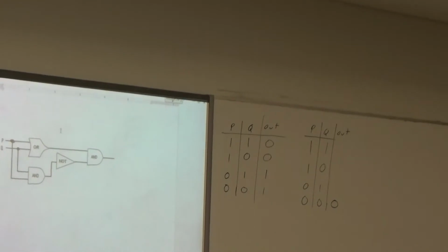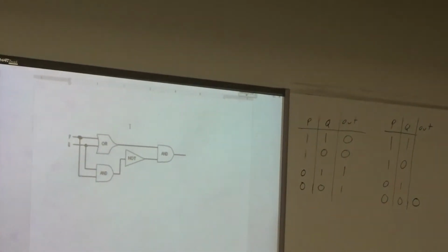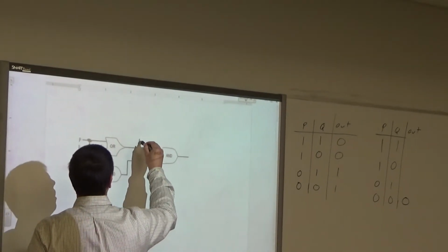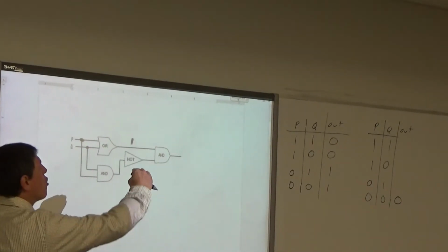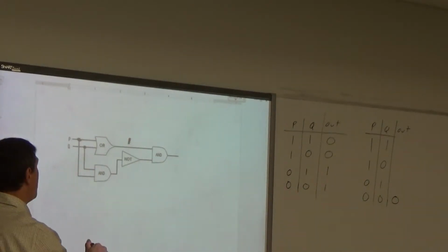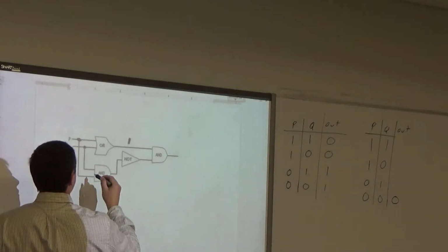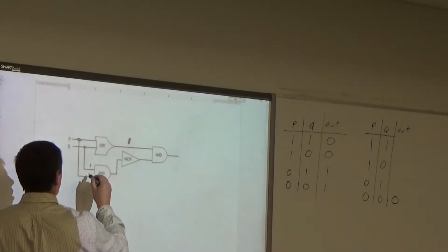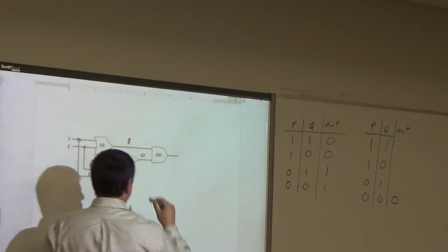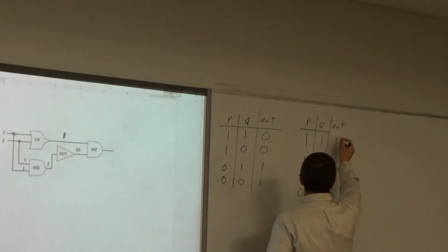If I put 2 1s through the gate, from now on I know no matter what I put through here, it's always going to be a 1 for the other 3 of those inputs, right guys? Because as long as one of them's a 1, then this is going to be a 1. So if I throw 2 1s through here, 1 and 1 is 1, we get a NOT of 0, 1 and 0 is a 0. Correct, guys? Okay.